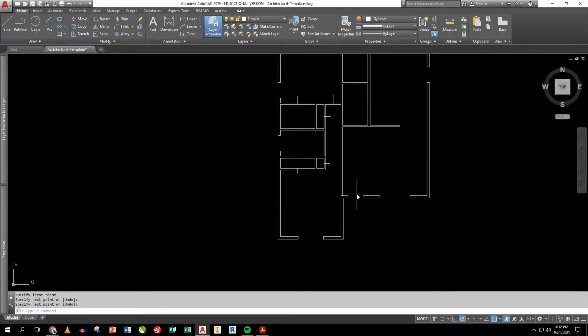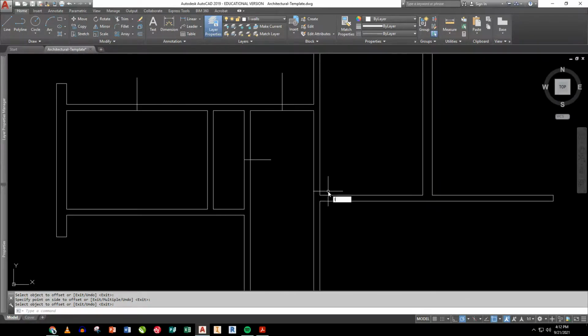and this one right here is 7'10" from the inside edge of the house. So I'm going to go offset 7'10" from here down. There's the middle of that door, actually the edge of that door. I've got another one that goes right here, so I'm going to draw a line through the wall, move this straight up. Now it's as close as I can get to the corner, which means that's going to be 3 inches over at least. So that's where that one falls.